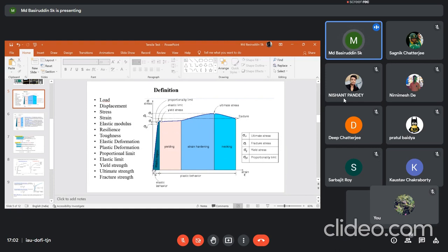Similar to the resilience, you can also calculate the toughness of a material during uniaxial tensile loading. In order to calculate that, you need to measure the area under the curve. Roughly, people try to find the ultimate tensile strength and the fracture strain and multiply them with each other, but that is an approximate toughness value.